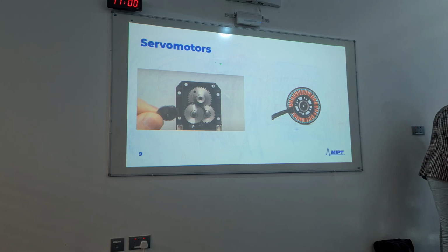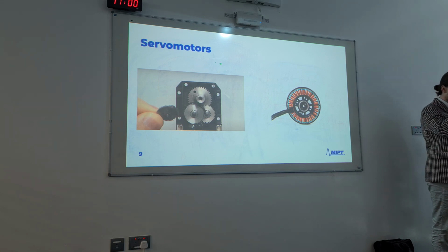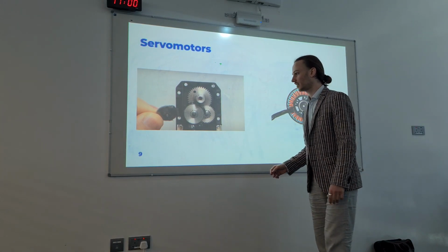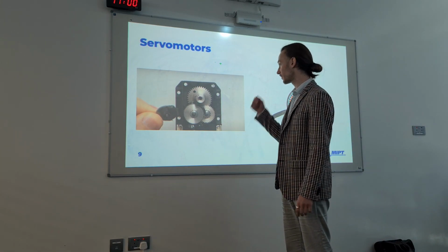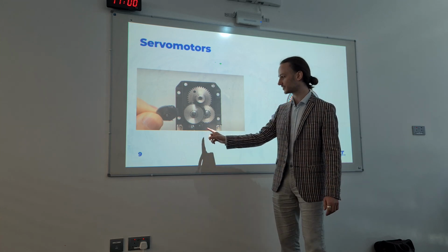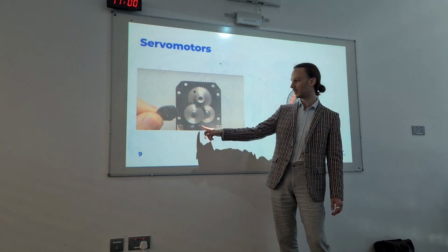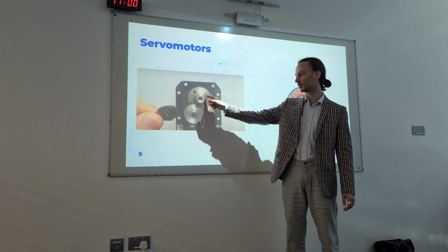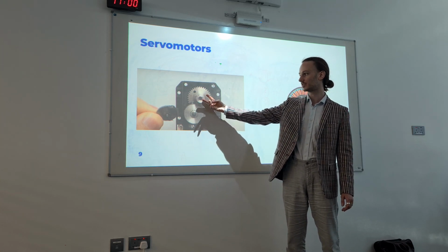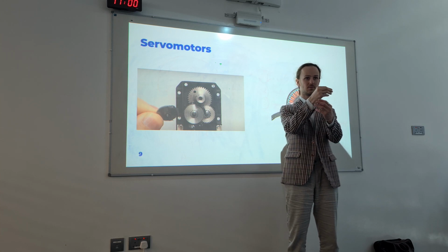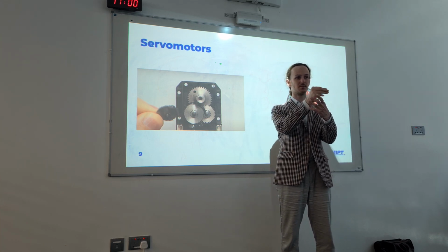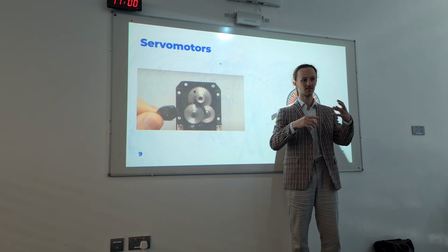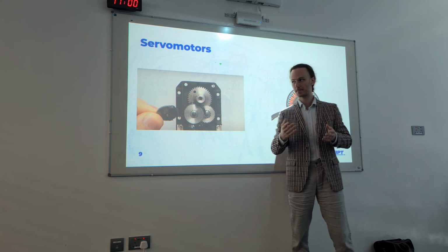On the left, you can see the servo motor, the gearbox. On the servo motor, the Dynamixel MX106. And here's the rotor, here's the gearbox, and this is the output shaft. So a part of this thing sticks out from the body of the servo motor, and the flange detail is fixed to that.